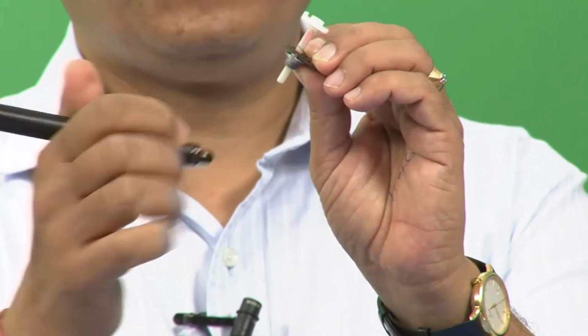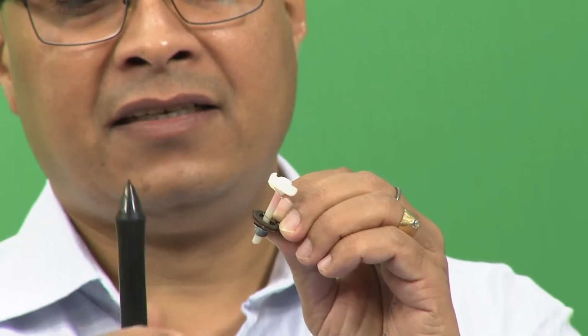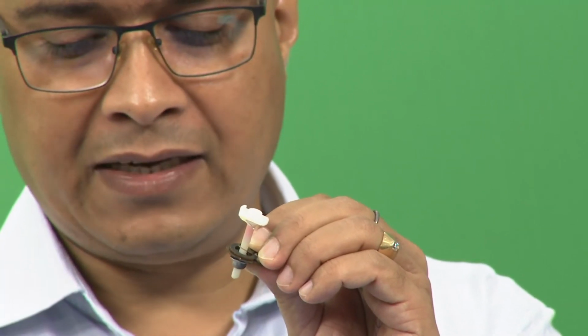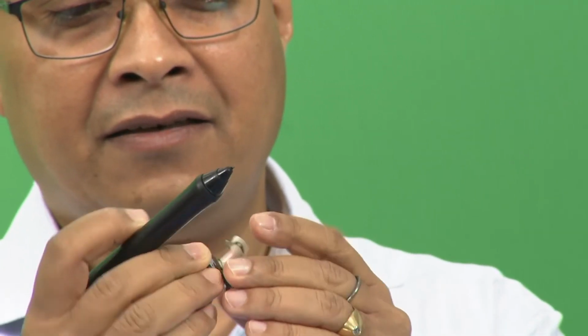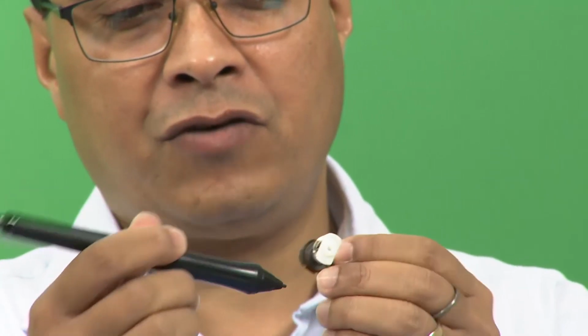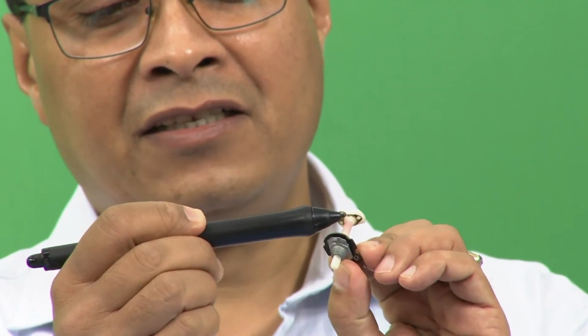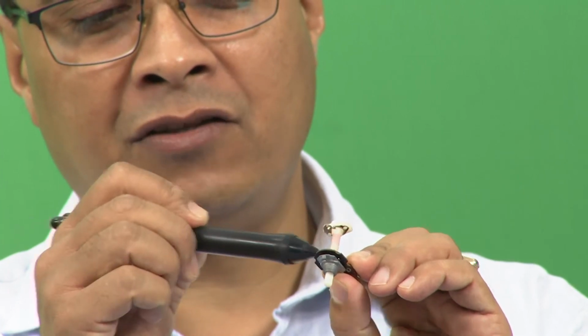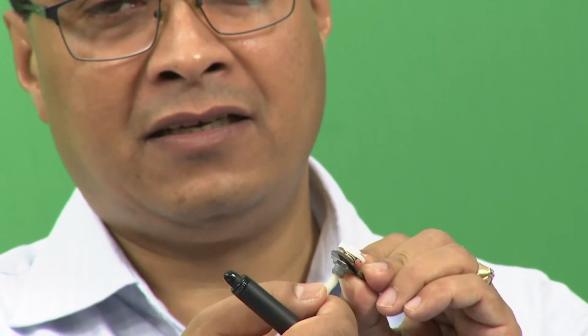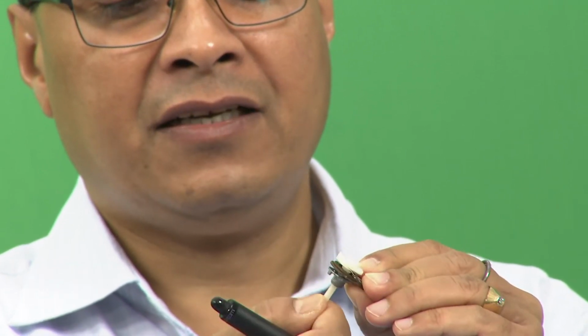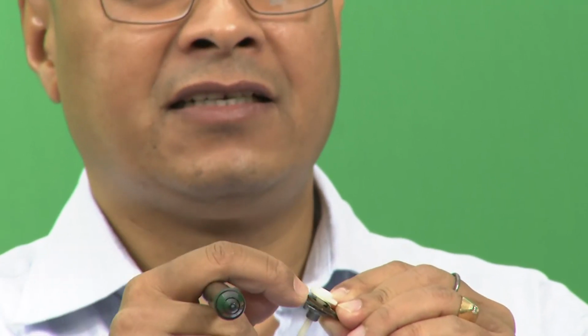Now, you can see more clearly, hopefully, this part. This is the wiper inside, and this is the resistance film inside. This is not the wiper; the wiper is this one on top. This wiper is the one that is moving on the resistance film, which is here. When it is contacting, it is like this. This is fitted onto the joint, and when it moves, the contact point between the wiper and the film changes, and that is how the ratio of the resistance changes and the output changes. So, this is a potentiometer which you would have used.